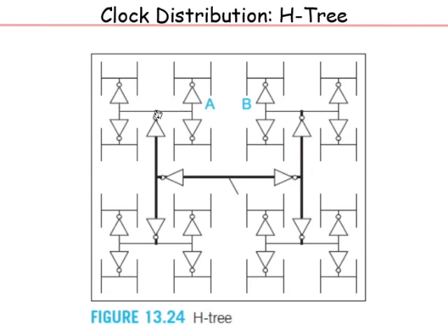Now you can repeat the same thing. When you come here, again you have another edge to distribute it like this. Now from here the information goes to these 4 leaves with equal delays, and similarly out here, and the delay from here to the next level leaf is the same throughout, and so on. Then again from here, if you want to distribute, you have one more edge.